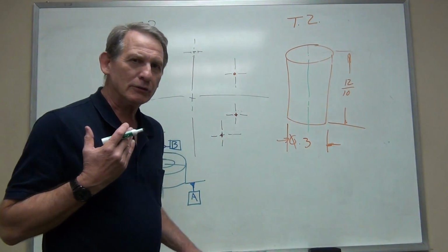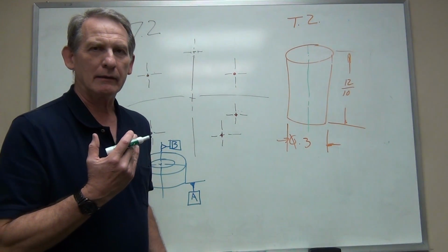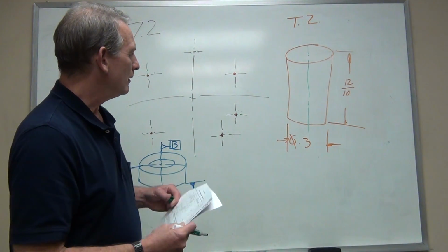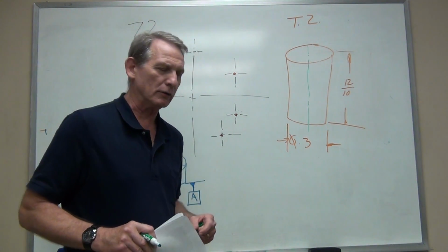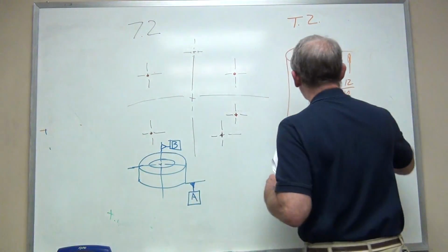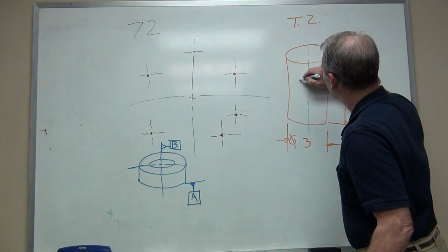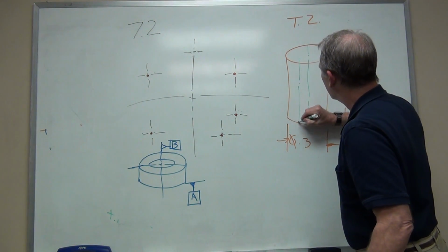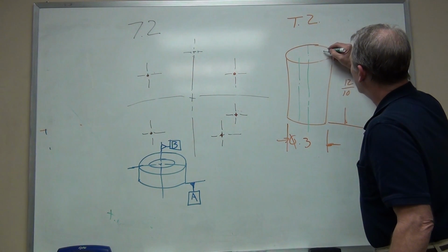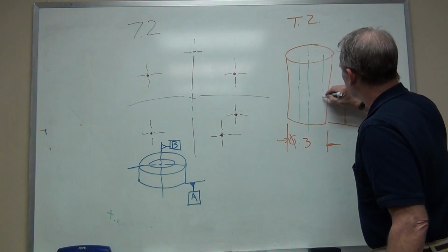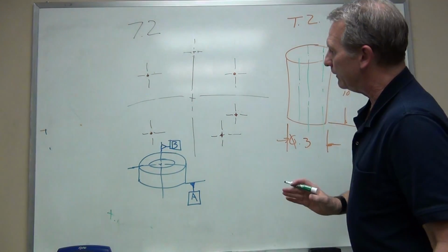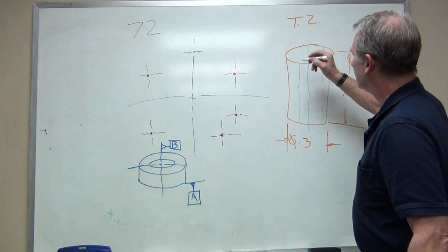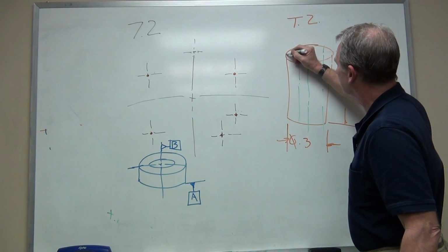So if we look at just the translational error that can occur, if the part moves a little bit in the fixture, if it's loose in the fixture, for instance, that could put the next center line right here. Could put it anywhere in this cylinder. All it's doing is moving around, and eventually, if it gets loose enough, it's going to bang into the walls of this cylinder.